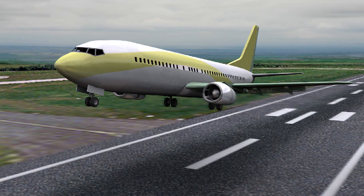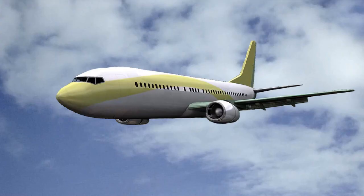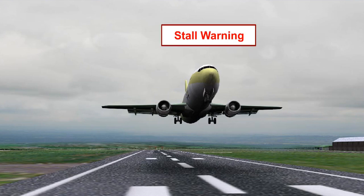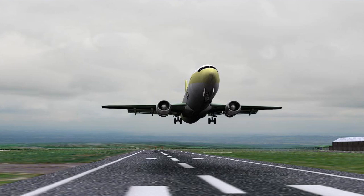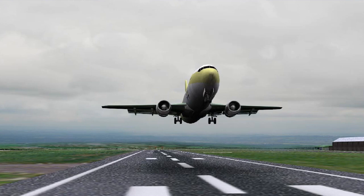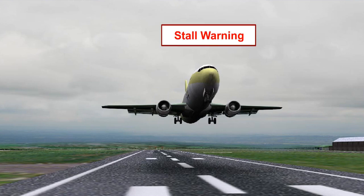The instrument is essential where precise control of speed is required, particularly on an approach path or climb-out, and for realizing optimum performance in the cruise. The angle of attack indicator will also give an indication of an impending stall, and in advanced aircraft systems the angle of attack indicator will form part of the stall warning and prevention system.